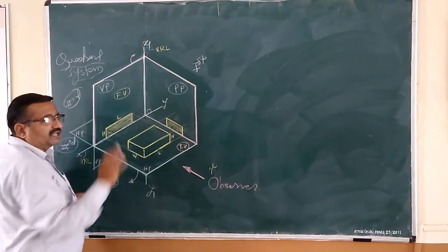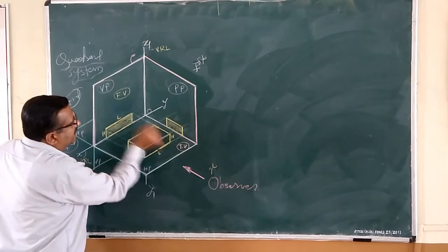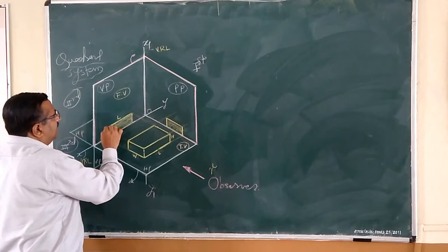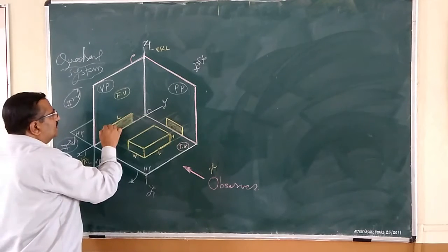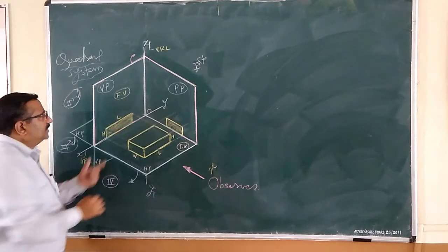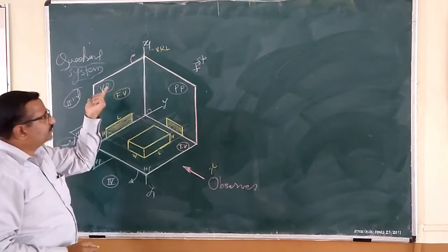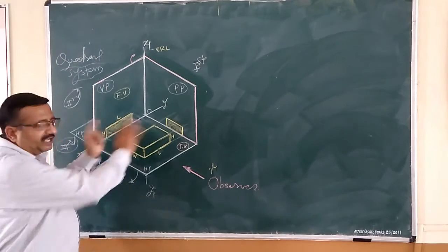Projection line, construction line we can say, construction line. And again from this right extreme left 30 line of this object, I have projected another projector. It has cut this projector here. So this is nothing but the shape and size of that front image which has been created successfully over this vertical plane. So by default, this vertical plane is made for the front image of the object.